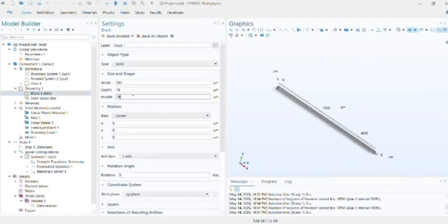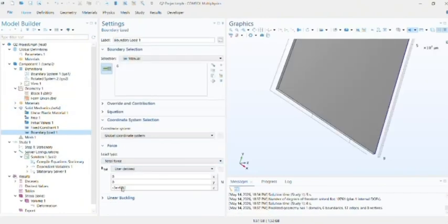Okay, for now cantilever B, we are going to change the depth of the beam to 1000 micrometers and we are also going to change the force to -3e4 newtons to maintain the exact same load per unit width. And now upon computing the study, we can see